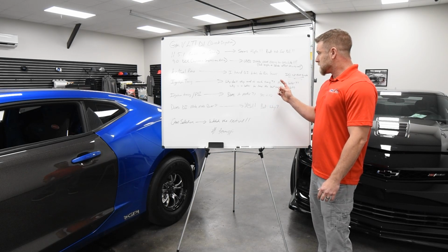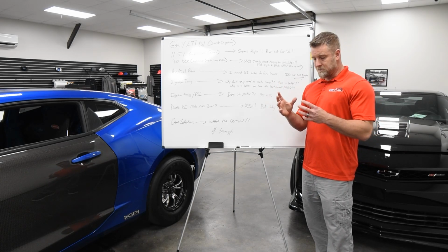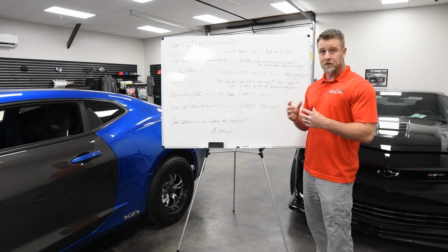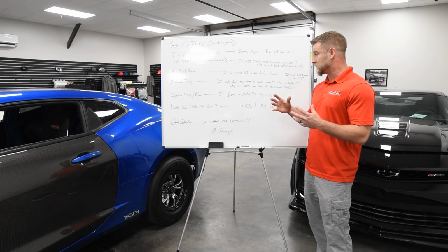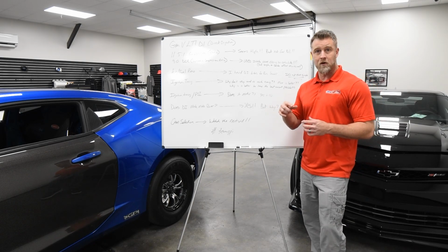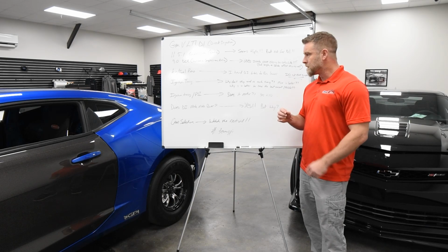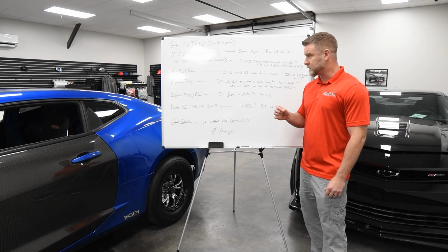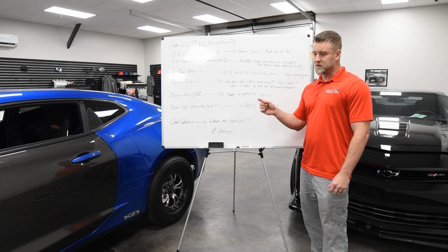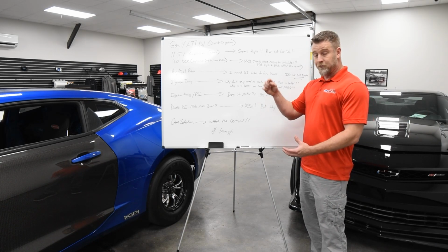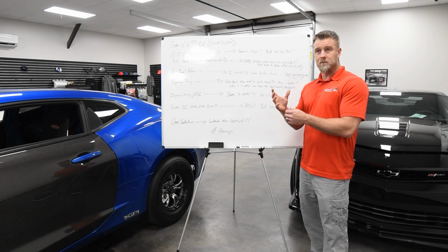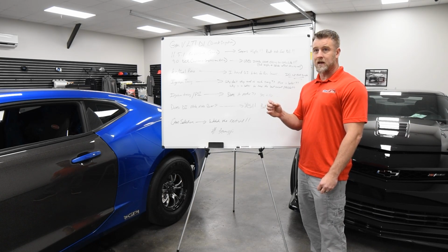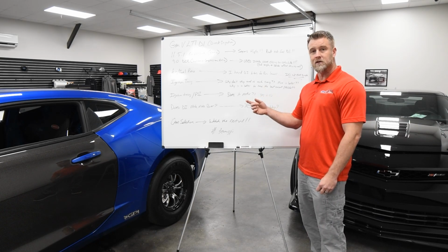It's always best to have the most efficient combustion package possible. The combustion chamber plays a big role in this, in regards to how complete is the burn, how fast does it burn. More timing isn't always better. So the sooner you fire it, before top dead center, the piston's still coming up. The piston has to work against that. So there are some mechanical losses in having to fire it sooner.